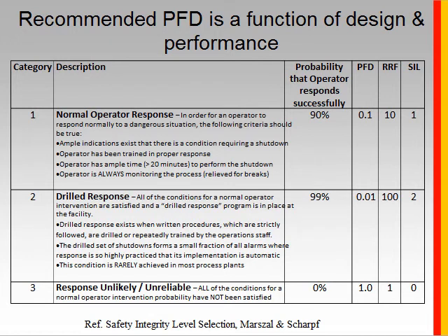There's a lot of guidance and recommendations on what the assumed probability of failure on demand should be when doing a LOPA analysis. Here's one example which shows different levels of performance, or different levels of PFD, based on design and performance. And it describes the prerequisites, or the things that need to be in place, to deliver this particular PFD.